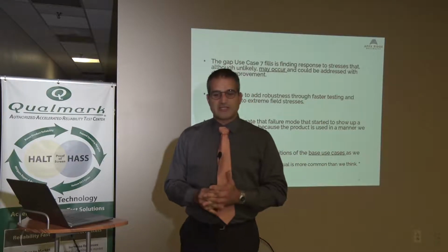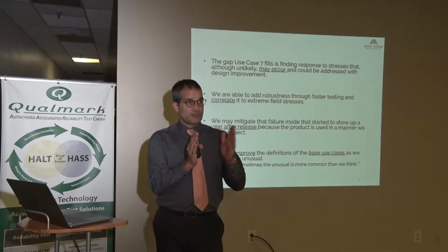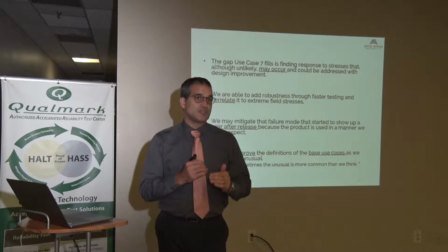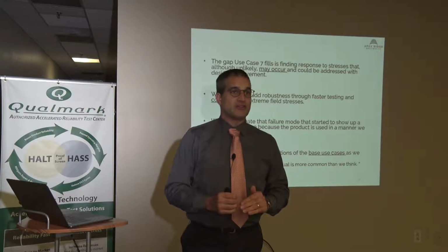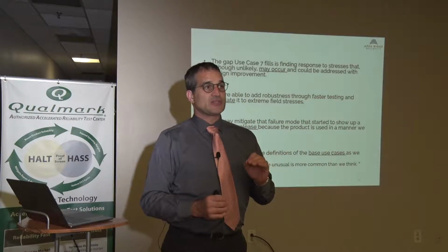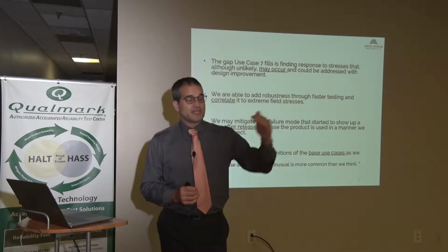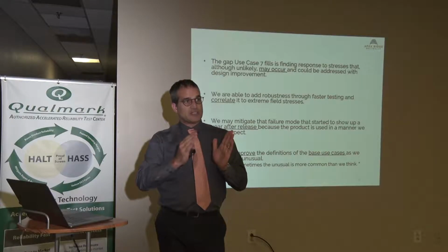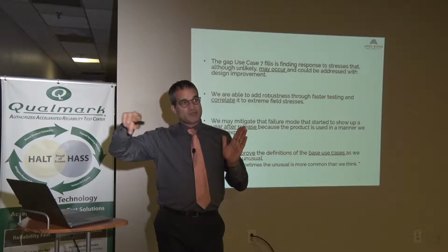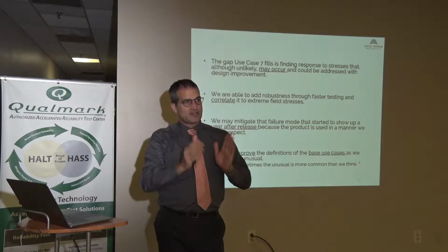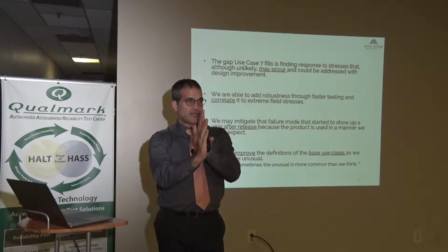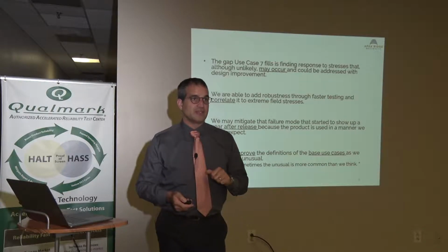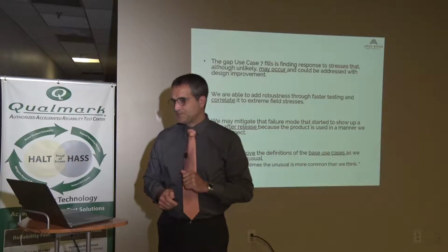So we're not just looking at the stresses as in an individual stress where you're looking for a response. Time can be the factor where we're looking to extend the period of time from failure from an accumulated stress. And it also can have a very big impact because the last part, that bathtub curve, the wear out part, you're effectively also creating margin on that and extending it out. Because with the wear out side, you don't want that tail coming in too close to the end of the product line. So if you push that out, less of the tail is potentially going to occur within the normal product life.